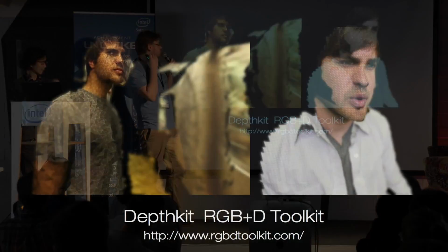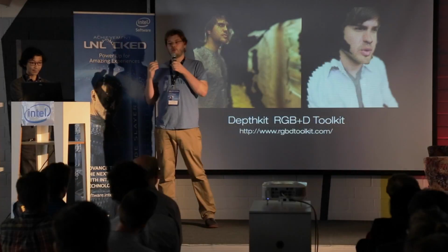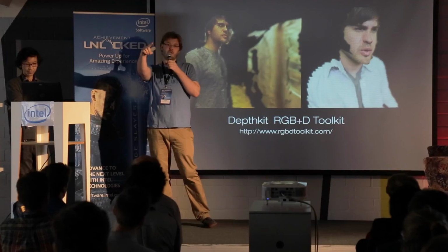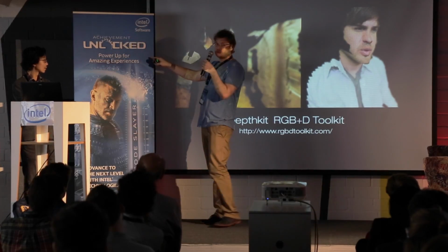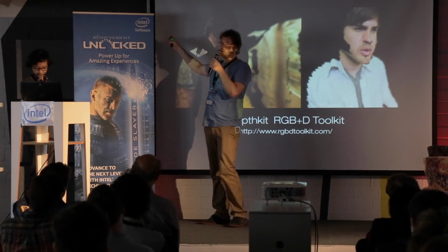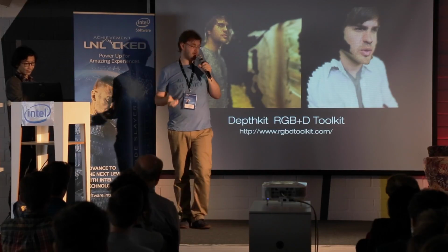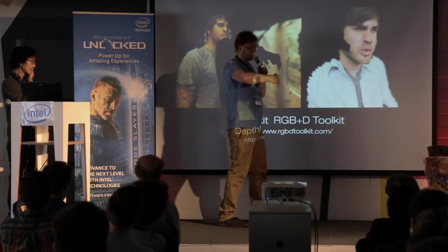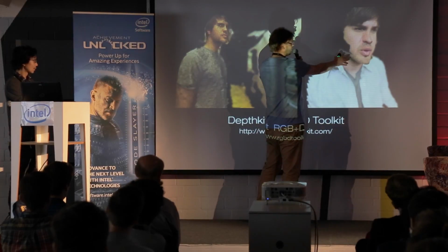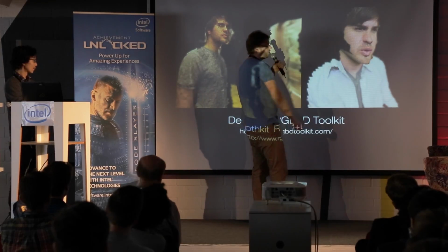So what you can do is combine it with a depth camera. That means a camera that not only gives you RGB, a normal color image, but also gives you the distance from the camera to each pixel. So for instance, if I look in that direction, maybe this would be 1 meter away and something behind it would be 2 meters away. For each pixel, it tells me roughly how far away it is. So what you can do is map the color image, like a webcam image, onto the 3D surface. So actually you get a three-dimensional nose, lips, and everything else out of it.